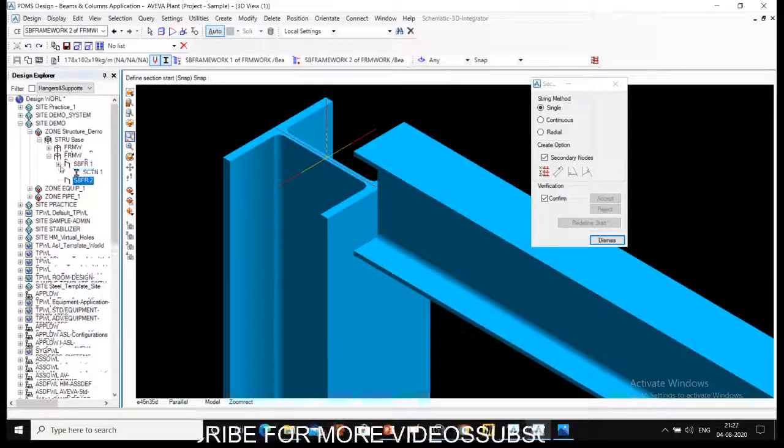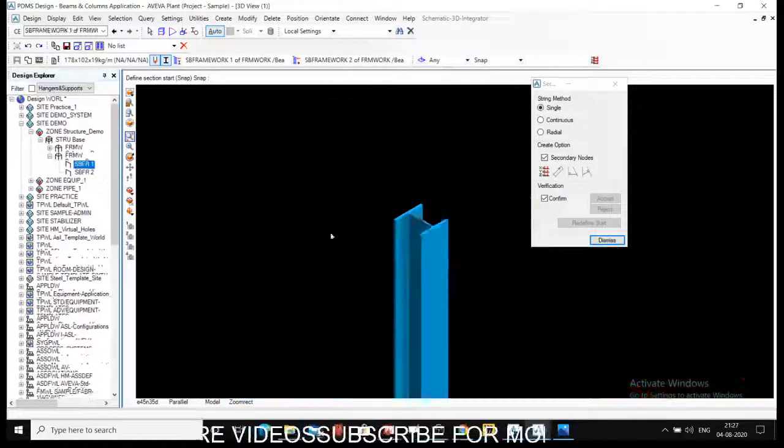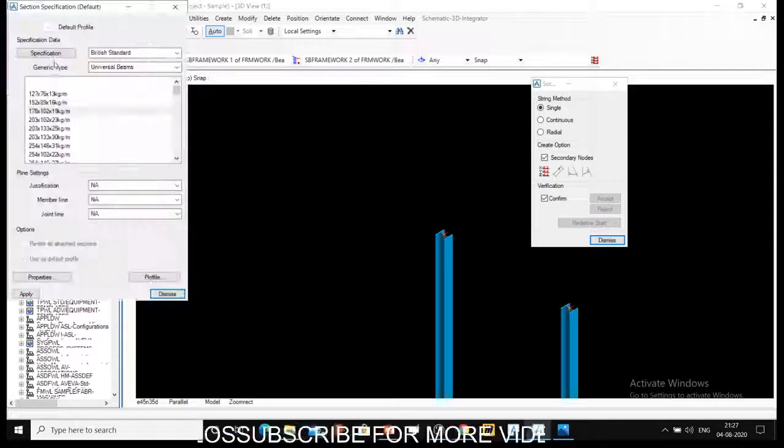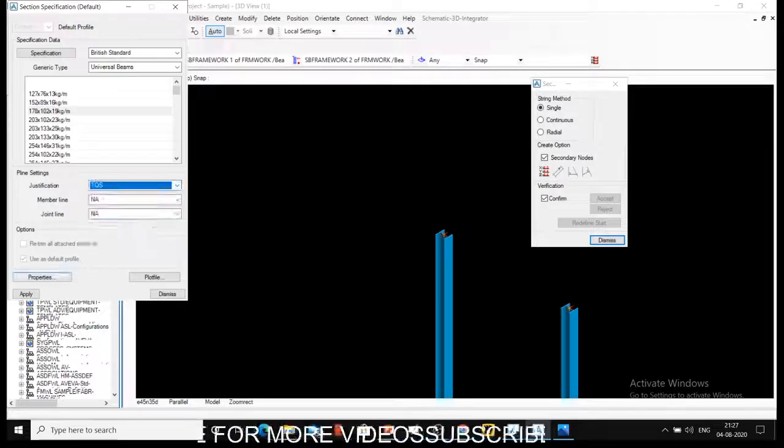So I will just delete everything. I will go to properties again and change justification to top of steel.